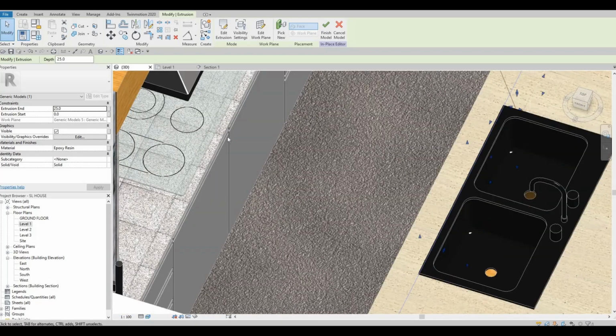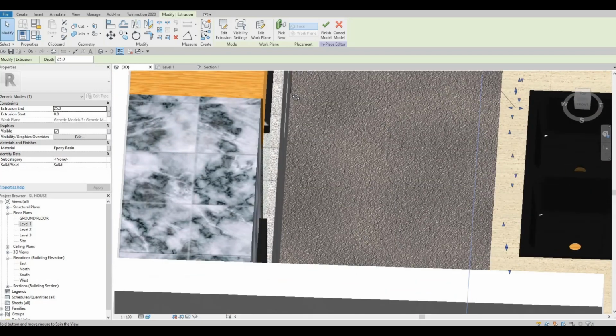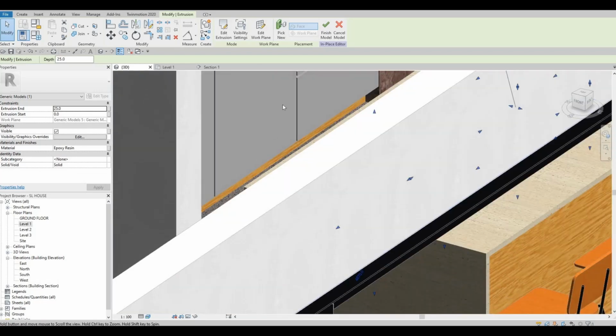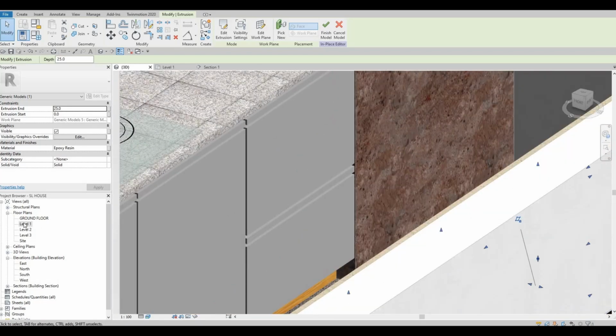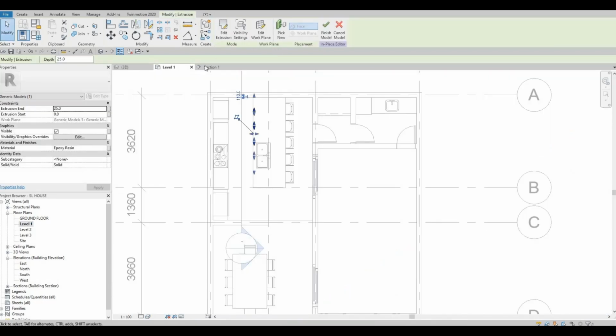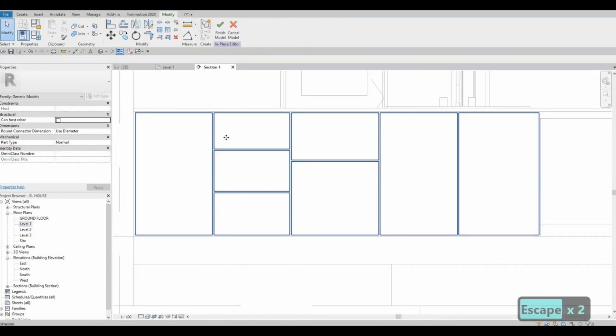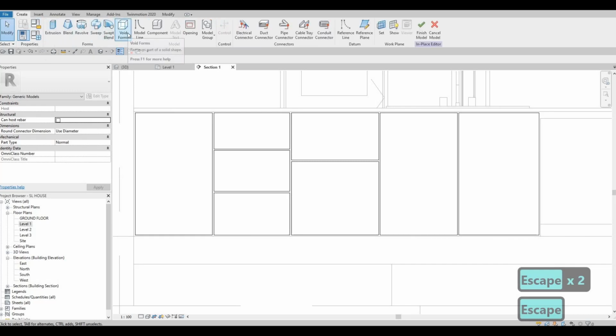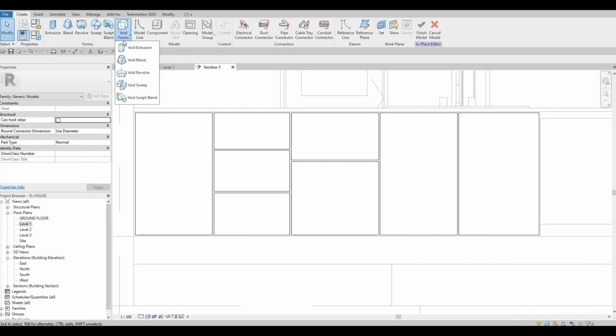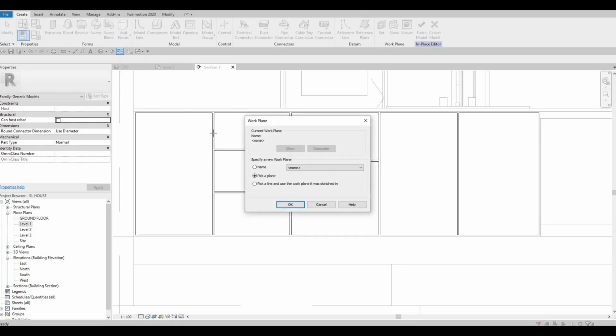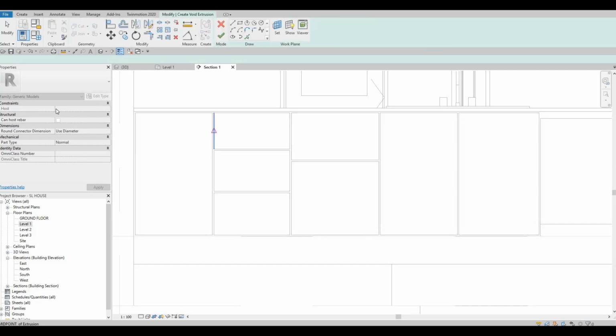And then we're probably going to do the same version of door right here, door opener. So let's go to section again. We haven't finished this one anyway, so we could just click on void and then void extrusion, pick a plane, and then let's select this plane.